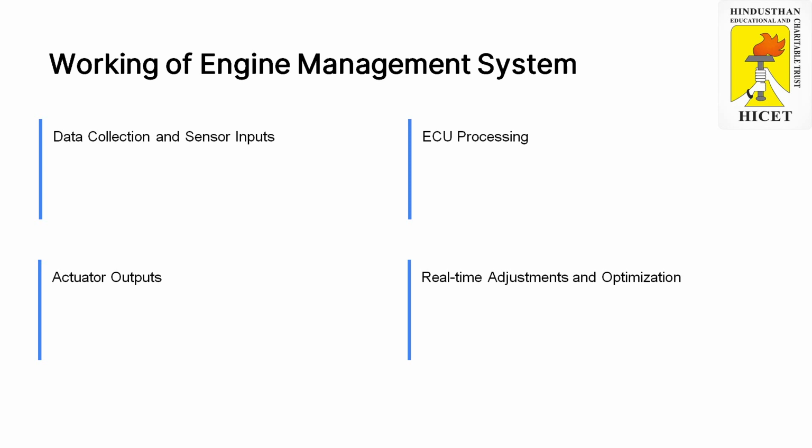In a similar way for temperature sensors also. Thermocouples are sometimes used, and thermistors can also be used for different kinds of applications. The different kinds of sensors collect all the data together and, through the controller area network, send the signal to the ECU. So all the sensor data is collected together and sent to the ECU. For every instant of time, it collects the data and sends it to the ECU. So that is the main function of sensors.